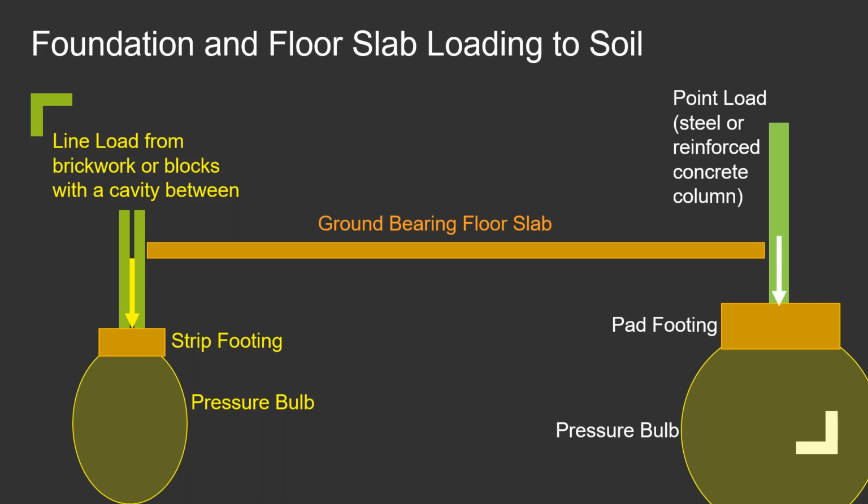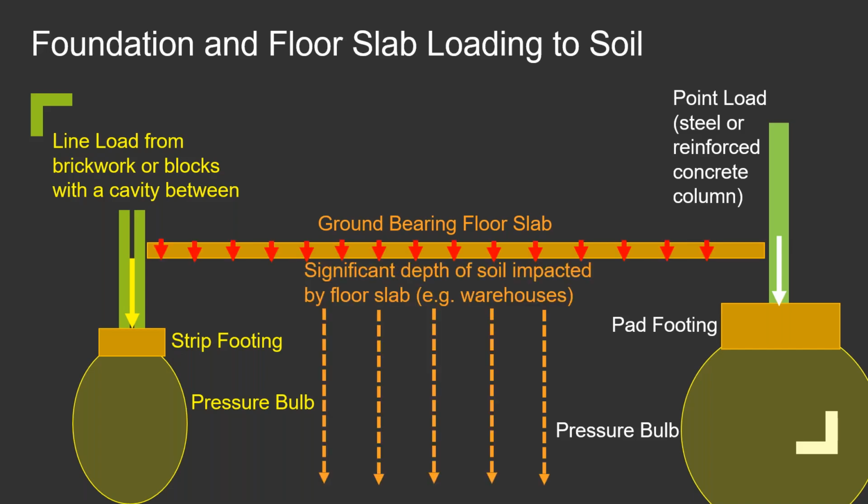And the issue here, just to bear in mind, is that because the floor slab is over a wide area, the zone of influence extends down a long way. So even though the stress is relatively small, it could generate a significant volume of soil stressed to that small value, and that could generate a movement of that floor slab. We might need to look at suspended floors. If we did that, then all of that floor slab weight would have to go to the perimeter loading applications, and then those loads would be higher. So it becomes very, very difficult to do that.